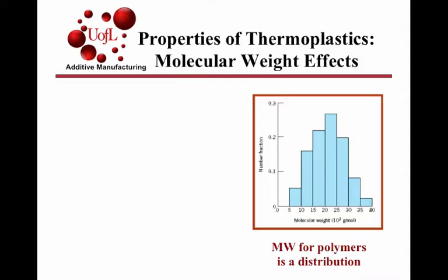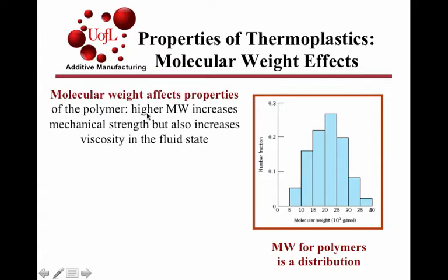Covered in the last lecture, polymers were materials with large molecular weights and with a wide molecular weight distribution, and it's because of this distribution that you have the melting point occurring over a range of temperatures. Also, increasing the molecular weight increases the melting strength but also reduces the fluidity, so it increases the viscosity and so affects the processability.